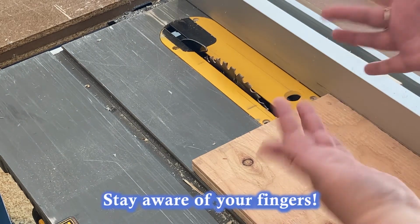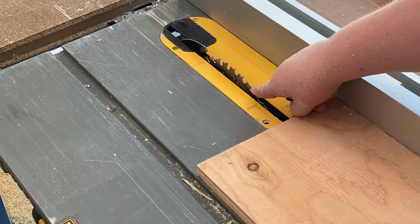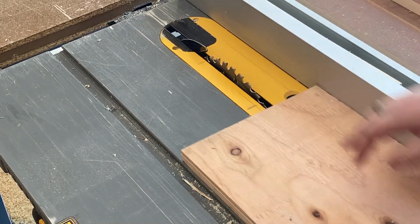You want to know where the blade is and where your fingers are. So when I'm doing this, I'm not looking all over the place. My eyes are pretty much locked right at the blade and the edge of the fence. So I'm looking at where the blade is and how this gap is looking right near the blade.